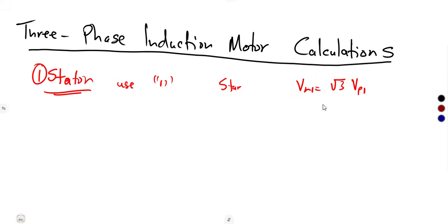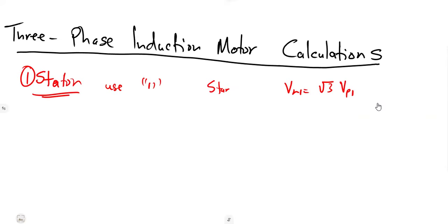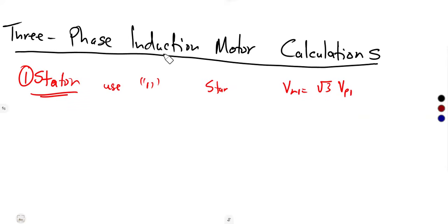So therefore, what can we say? Because we are using three-phase, remember our golden rule of three-phase: we use phase values. Even under three-phase induction motors, we are still under three-phase. The golden rule is still the same. You use the phase values in your calculations. So as a phase value, what are you going to have? It is going to be the line voltage over what?